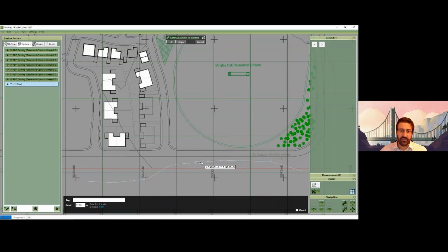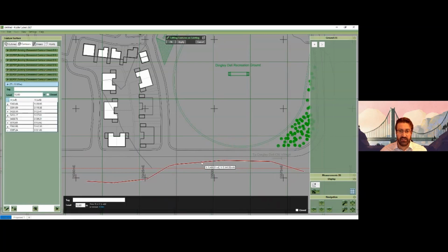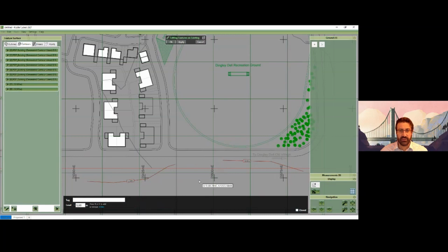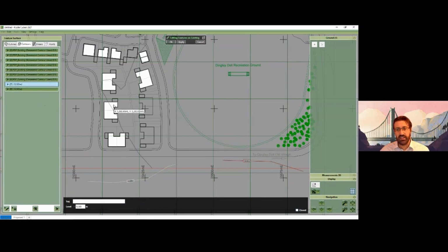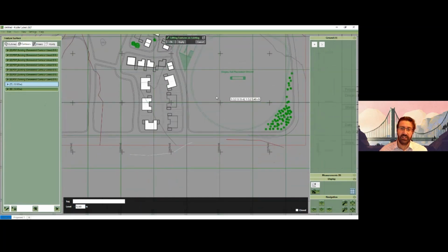The other thing that you can do is if you want to split a line, you can select that line to split in the middle. So sometimes you've done maybe one outline. This might be quite common with outlines, and you want to split it. Now you can start another one, and now you can split it in the middle, and that's quite useful as well. It's quite simple, but they're really useful tools, I feel, especially in the context of bringing in data from PDF when it can require quite a bit of correction. So we'll delete those 2.